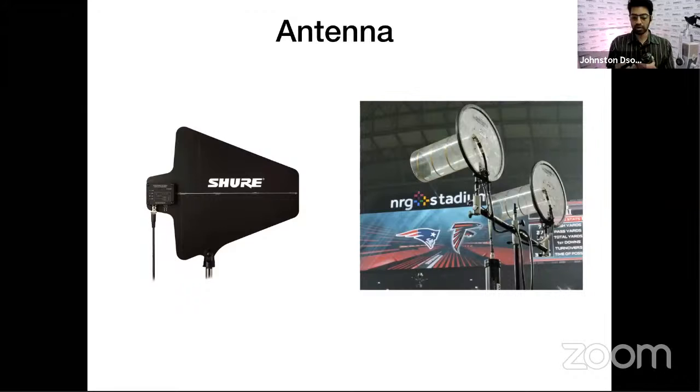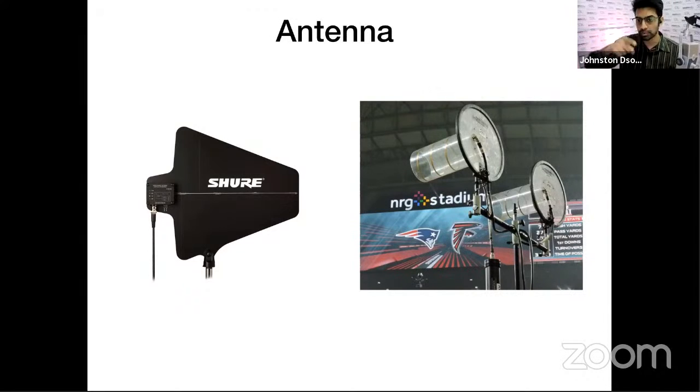So if I have a transmitter and receiver, and the transmitter is this way and the receiver is that way, the receiver is not going to pick up RF. So in order for RF to flow properly without any interference, you have to make sure that both the transmitter and receiver are in the same orientation. But if you have an antenna like the helical antenna, it has something known as 360-degree polarization. If you see that little copper wire like a spring inside the plastic cylinder, what it does is make sure that the RF goes in all directions, and so no matter how the transmitter or receiver is oriented, it will pick up all the RF without any drops.